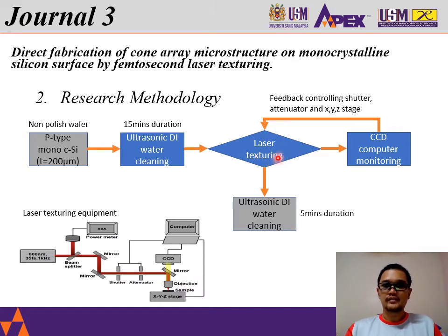The laser texturing equipment comes built in with CCD computer monitoring feedback to control the laser texturing or laser ablation. It gives feedback control of the shutter, attenuator, and the XYZ stage. The next process is cleaning again with ultrasonic DI water for 5 minutes. So this is the end of the process.